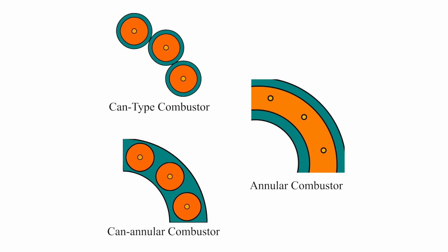Like CO, nitrogen oxides (NOx) are produced in the combustion zone. However, unlike CO, NOx is most produced during the conditions that CO is most consumed: high temperature, high pressure, and relatively longer residence time. This means that, in general, reducing CO emissions results in an increase in NOx, and vice versa. This fact means that most successful emission reductions require the combination of several methods.